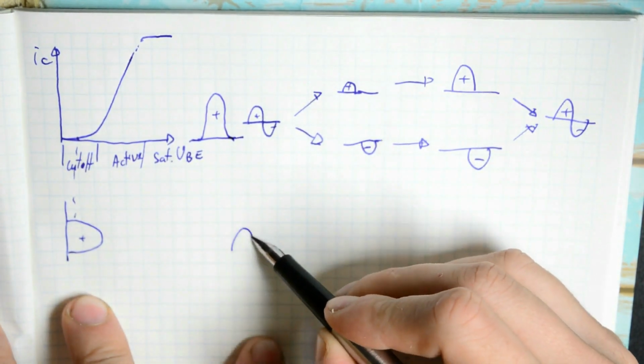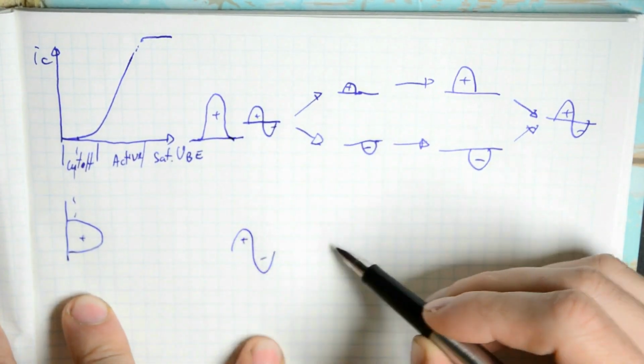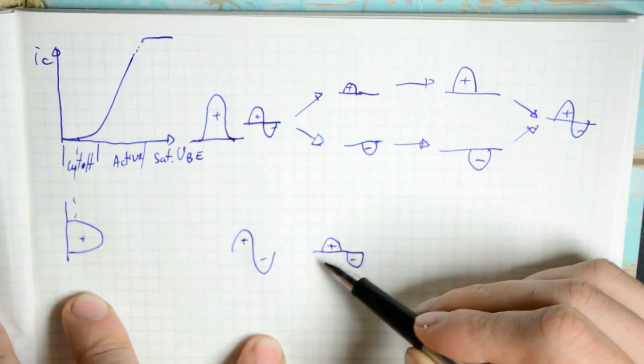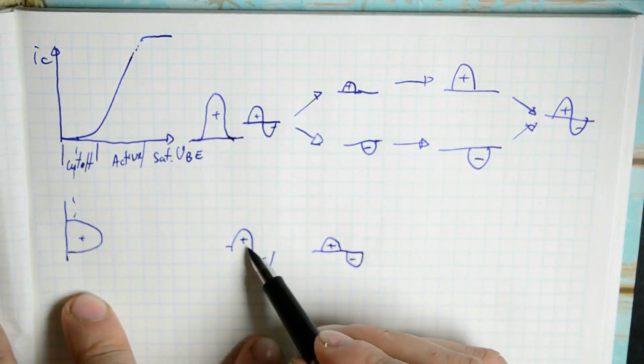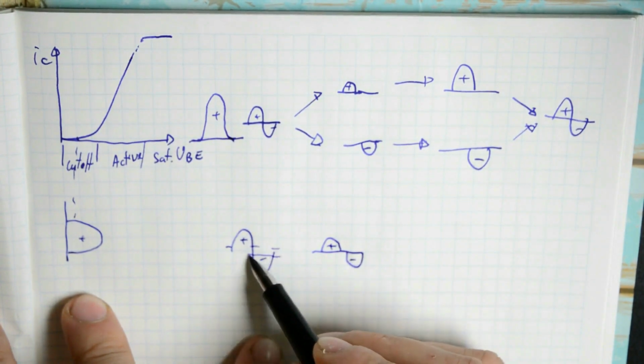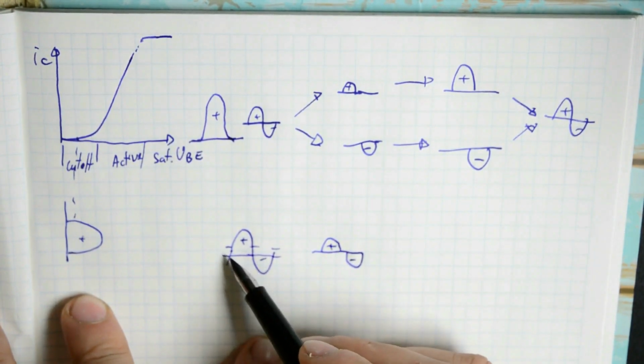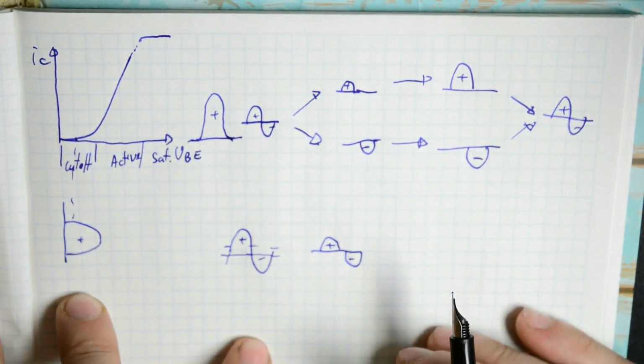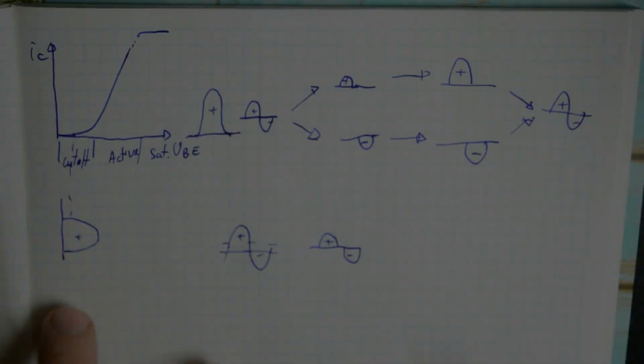That means that our input signal, which is a perfect sine wave, will look like this at the end, with the middle bits, the low voltage bits, cut off. This is actually the voltage needed to switch on the transistor. So let's see one of these circuits actually implemented in a simulation.